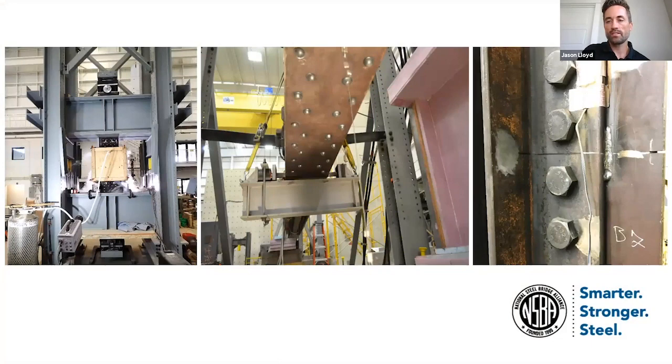On the left now, you can see the cooling chamber wrapped around an axial specimen with nitrogen vapor escaping. The liquid nitrogen tank is in the lower left. Following cooling of the specimens to the lowest possible toughness, the specimens were then loaded to 0.55 Fy, or sometimes more, of the unfractured cross-section.